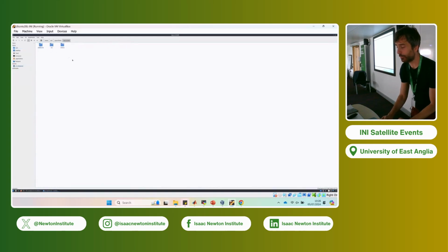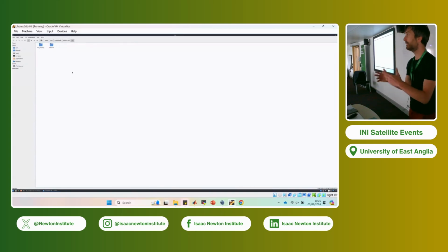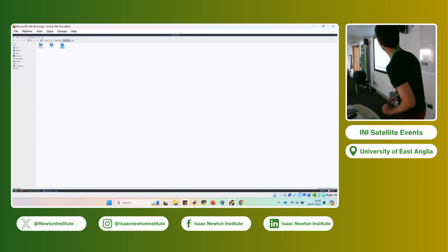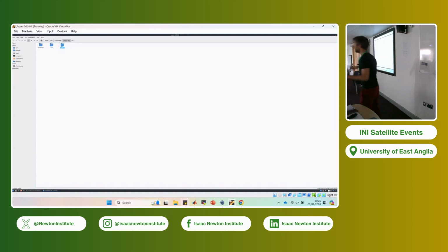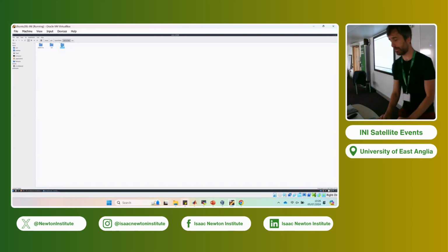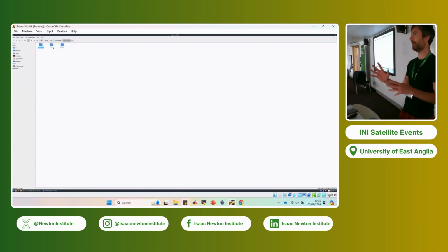So in this user folder, I have a folder called run where I put all the test cases. And I have another folder called solvers on the top right where I put all the solvers that I modify, so that I try to keep everything in a tidy way. The folder called platforms is a folder of OpenFOAM where every time you compile a solver, it puts the executable there.